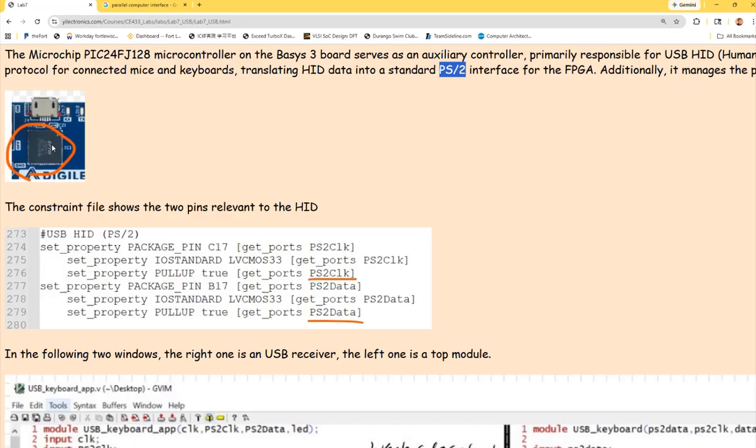So we don't really use the USB. It's not really a USB protocol. We always convert it to UART, right? So it's called serial. We always do TX and RX with the laptops. So the USB port is able to simulate a UART transmission, and eventually we just have a TX and RX that communicates with the laptop. So you can see the thing is, you got a UART here, and UART converted to PS2.